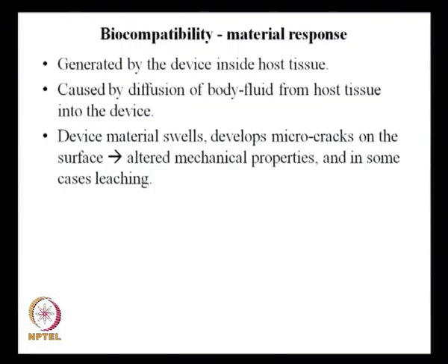Device material swells, develops micro cracks on the surface, has altered mechanical properties, and in some cases leaching. So, these are the problems that would happen if the body fluid enters into the device. Because of that, the device material swells and develops micro cracks. The moment it starts swelling, you don't know what is going to happen, because you are stretching it. In some places it is getting stretched, in some places it is not. So, stresses would develop, and at any point a crack could develop. So, swelling is something you have to be careful with.